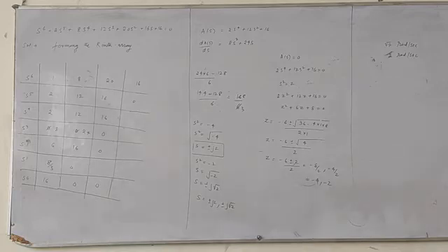Okay. Have a look at your mobile phones. Are you not understanding? Are you not getting anything? We cannot ascertain or confirm whether the system is stable or not. Although with a row of zeros, there is always a doubt that we cannot confirm the system is stable. But we definitely can confirm that there are no roots on the right half of the S plane. But that doesn't indicate that the system is a stable system.